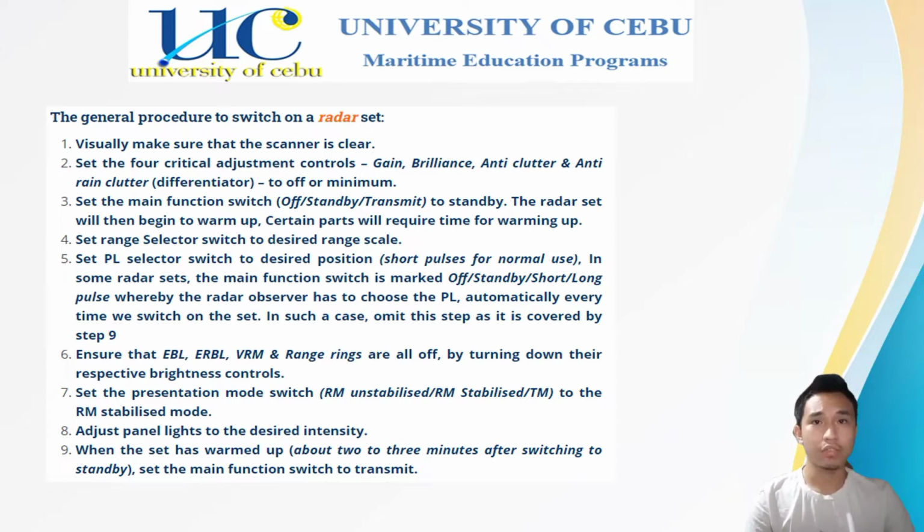Third is to set the main function switch of standby/transmit to standby. The radar set will then begin to warm up. Certain parts will require time for warming up. Fourth is to set the range selector switch to the desired range scale. Fifth is to set the PL selector switch to the desired position, short pulse for normal use.